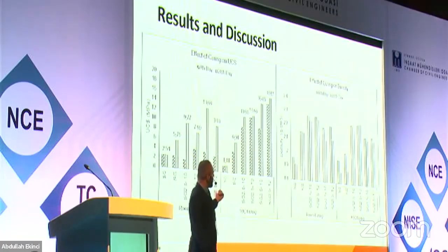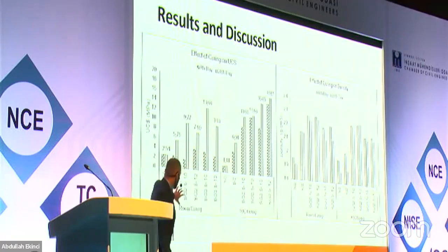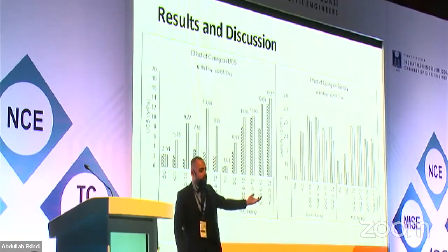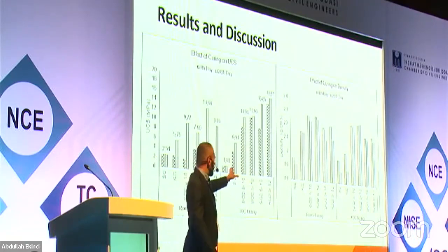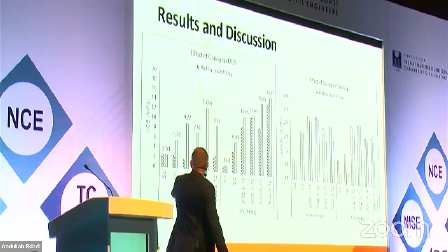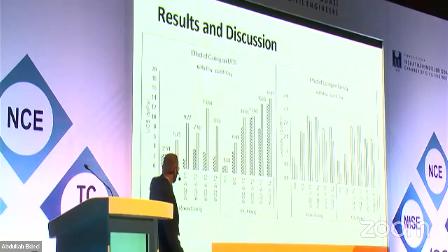So the things that we'll be discussing here are mainly focusing on the room temperature, since we don't want to use any heating, or we cannot even use heat in soil stabilization. So it's only done to see the increase in the strengths over age. The one that we have here, the effect of curing: we will see that at the early ages, 7 days, 28 days, a rapid increase we have over age.